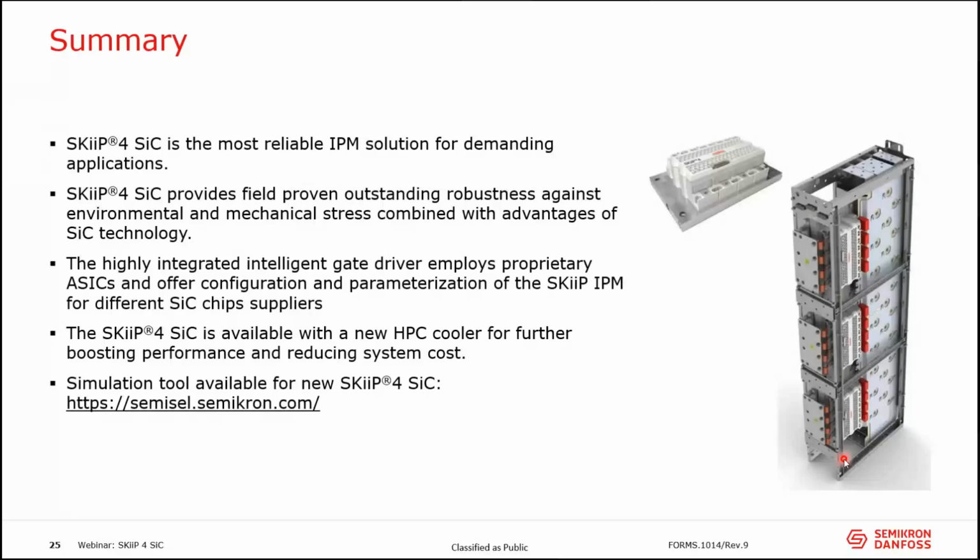Exactly. So then there's a question about short circuit. So what is the short circuit reaction time? And is there desaturation protection, or what's the blanking time? This is quite a sensitive topic. We do not want to share all the know-how that we have. And of course, it also depends on the chip type that you have in the module. But yes, we have a lot of different possibilities with the desaturation protection and with fast reaction. And this is all that we take care of in the driver, correct?